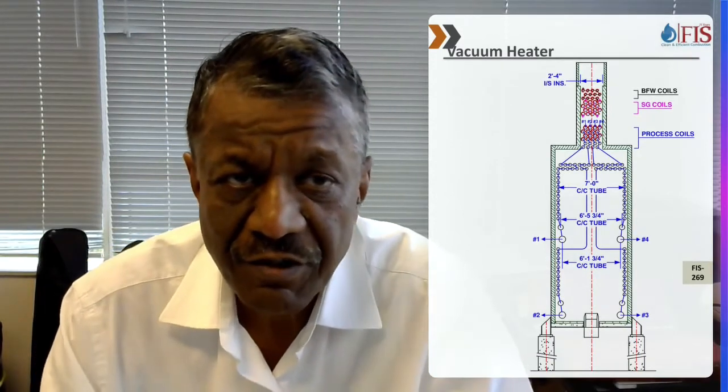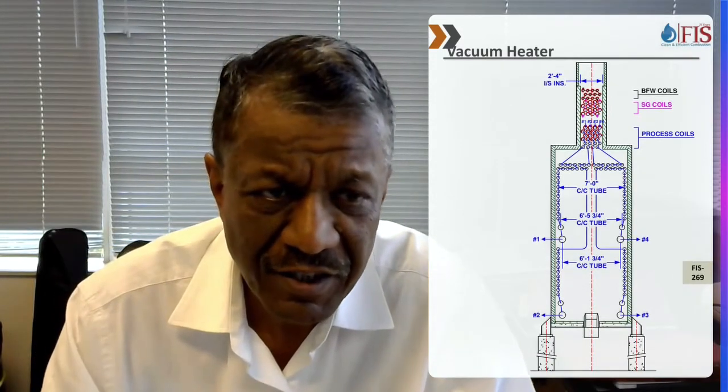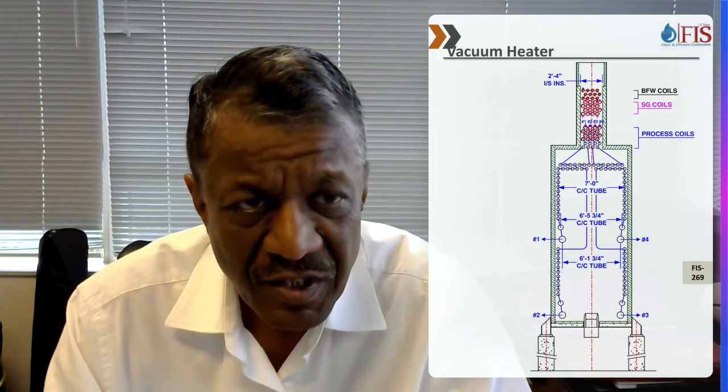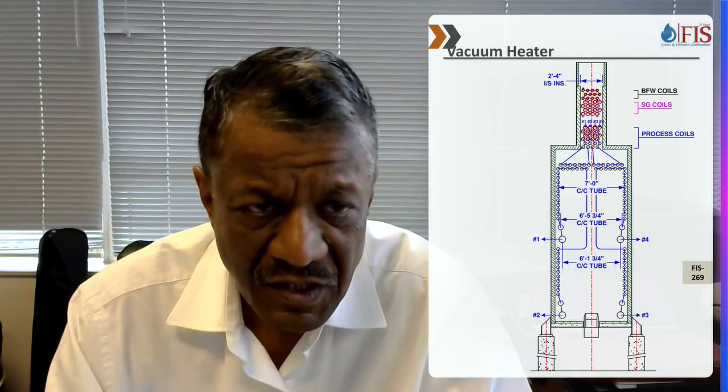Even though we say the radiant section is a continuously stirred tank reactor, it's never the case in actual. What happens is we get different heat distribution patterns in a heater. I'm showing you a heater here which we revamped several years ago, and you can see it has 4 passes, downward flow, and this heater was coking a lot.